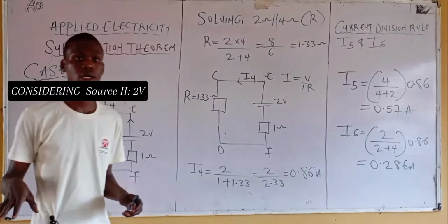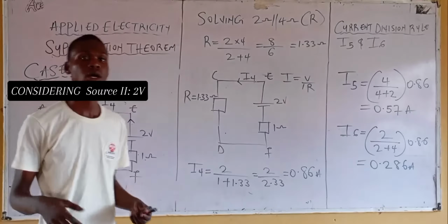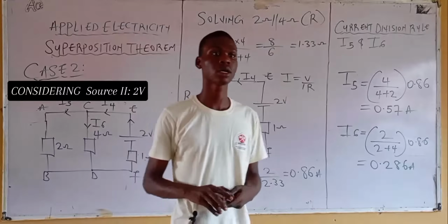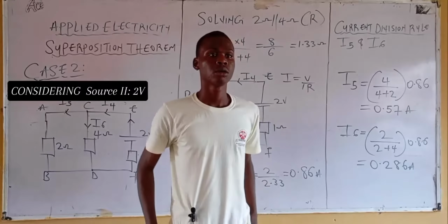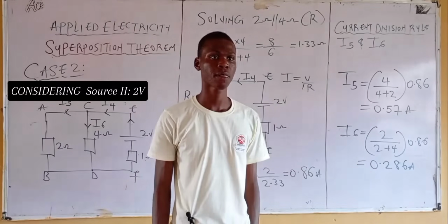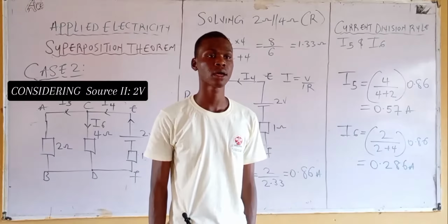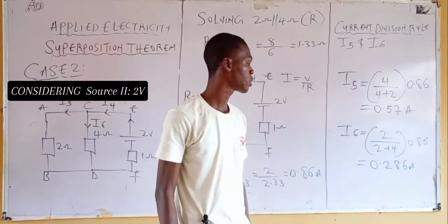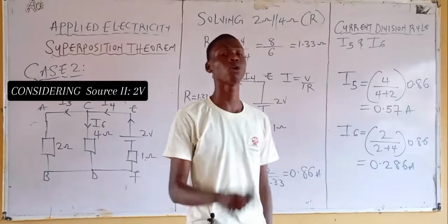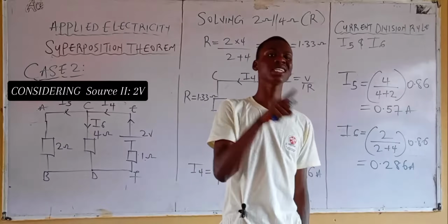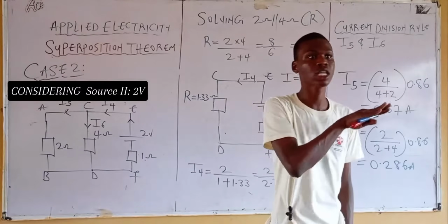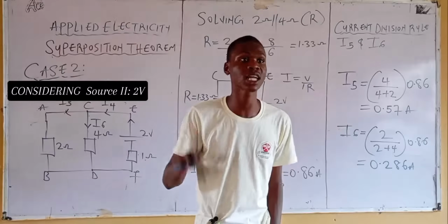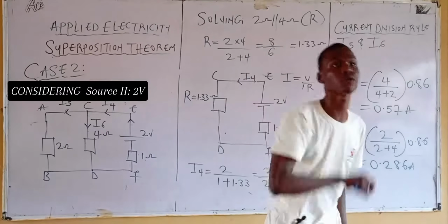No question. Hello. Yeah. My question. Yeah, what's the question? My question is, according to the superposition theorem, both the I2, I3, okay, is going to correspond with I5, I6. In the situation we have now, is it the I3 and the I6 that correspond? Corresponding in the sense that their values are not equal. Corresponding in the sense that in each branch we have two values of current.